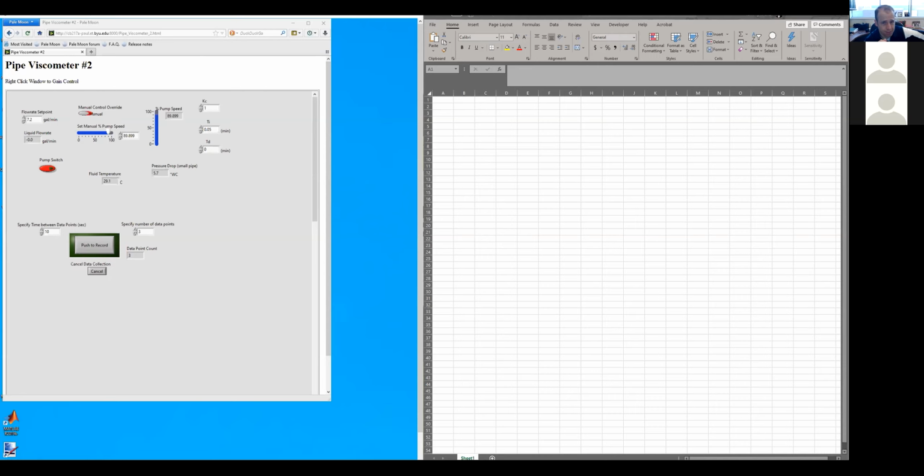Mach number is the ratio of the speed to the speed of sound in that material. And there's actually two critical numbers you want to worry about there. Mach 1 means that we're going to be choked. You probably remember that from maybe your 285 class, the lab you did. And then the other one is Mach 0.3. Does anyone know what that tells me? It tells me if I have to deal with compressible effects or if I can consider my fluid as incompressible.